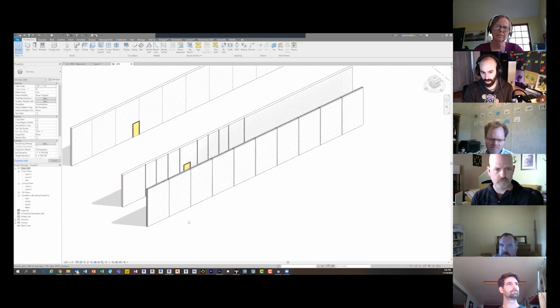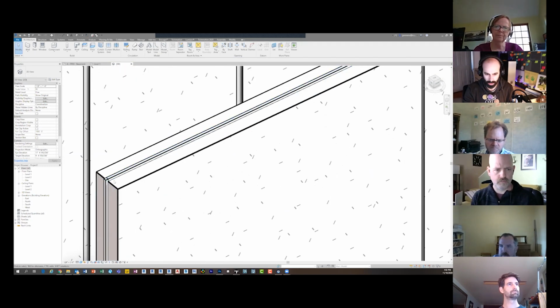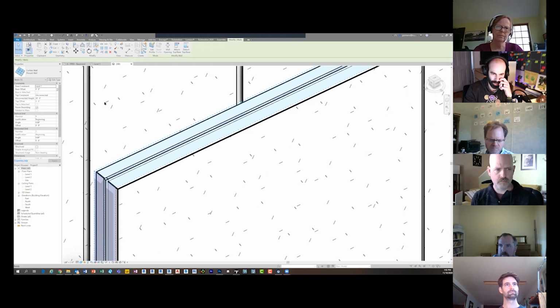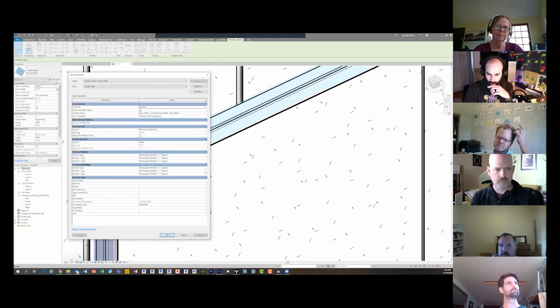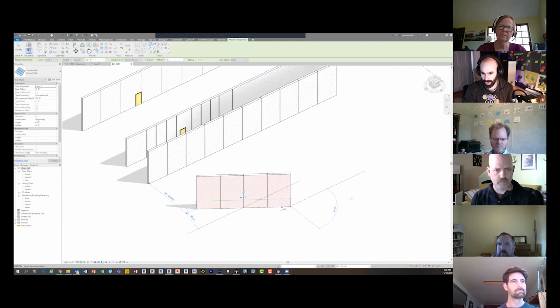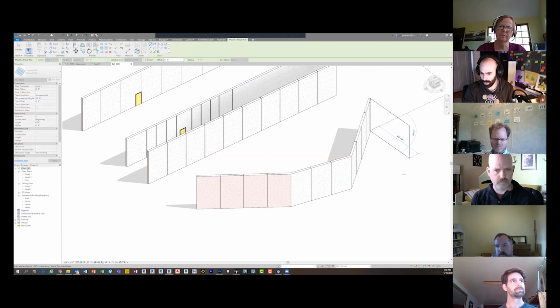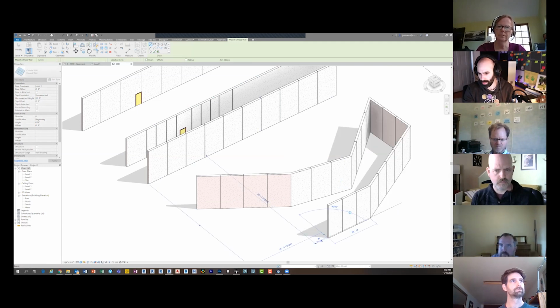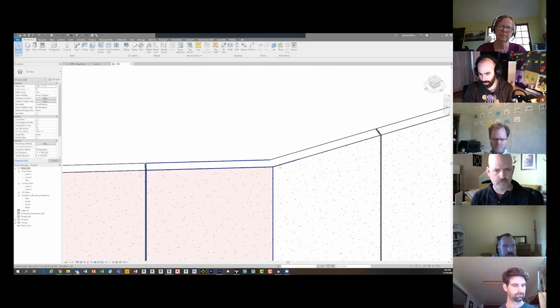And now you can see we have a wall. So I do have mullions here, so we need to do something about that. I didn't turn off my border mullion, so I should have put none for those because we don't want any around the border. None. And you also want to build as much as you can into the type, because then it's much more flexible, right? So if I create it similar, I can just keep drawing these, right? And you could see, actually, look at that.